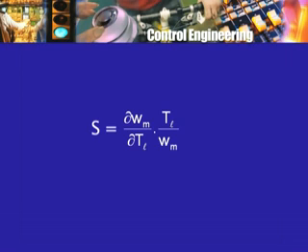So, in fact, it is not at all difficult, and today we are not worried about computation at all. One can look at the expression for the angular speed and then evaluate the angular speed for a new value of torque, rather than evaluate the sensitivity coefficient and then say that okay, for so much percentage change in torque, because of the sensitivity coefficient being, let us say 0.1, the change in speed will be 1/10 of the percentage change in the load torque.